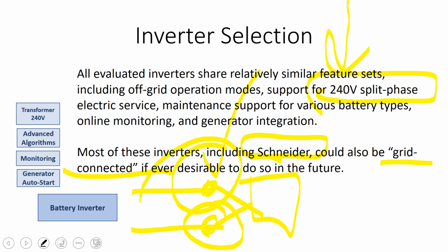Well, I like the two AC inputs because down the road, that second AC input could be a more advanced lithium-ion battery bank. It could be that we move the older lead-acid batteries to the AC input side on their own battery inverter, and then on the load side, we have a lithium-ion battery bank to assist the grid. If you have more AC inputs, it gives you more expandability down the road. That may or may not be an issue. For me, on my first off-grid house, I thought, well, the worst case scenario is I really mess up the design and he has to connect to the grid anyway, and we have that output there to be our insurance.